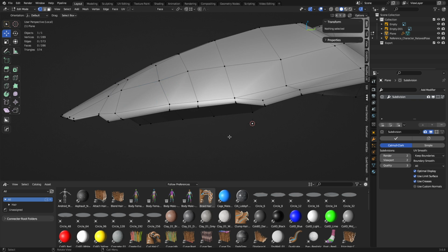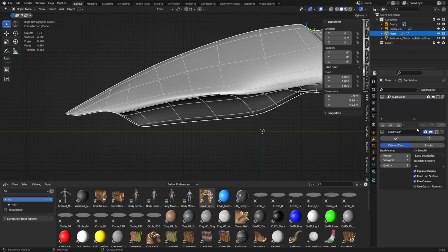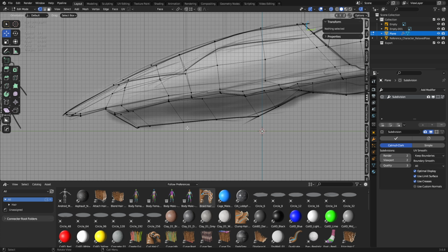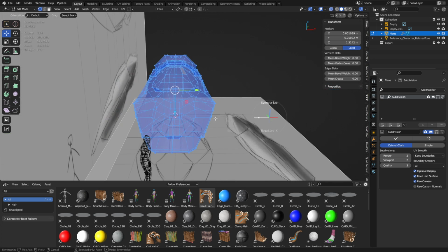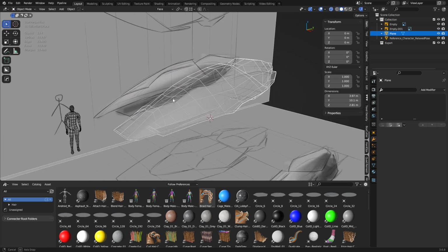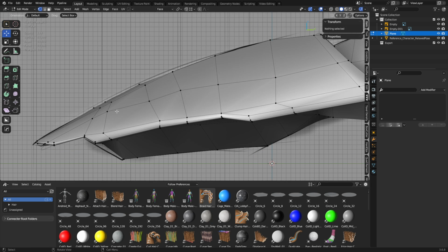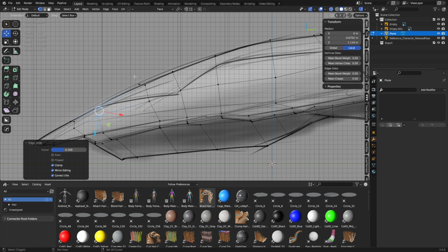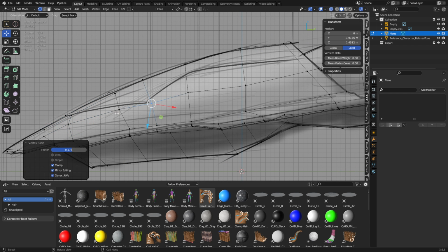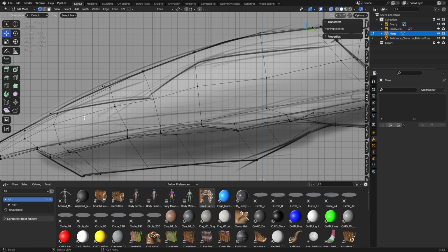And on top of that, just like I did that subdivision splitting in one video I had, right? Get rid of the subdivision in a second. See here, this edge might go forward. This one actually might come down to where that one was. But there's nothing that stops us from coming through here later on and using a knife tool, pressing K and C, cutting out the profile of this in this area, and trying to get it going the right way anyways.